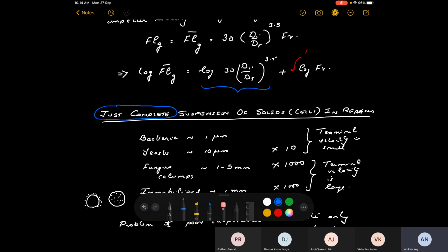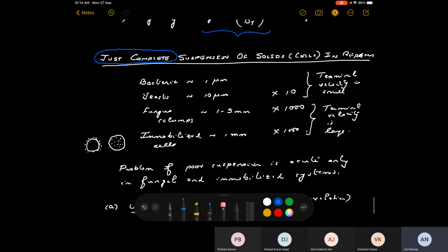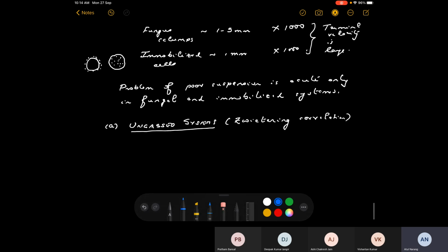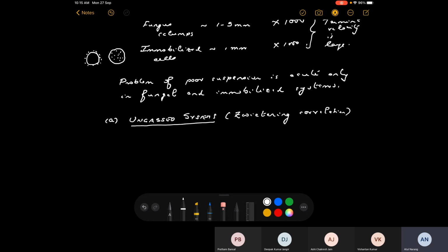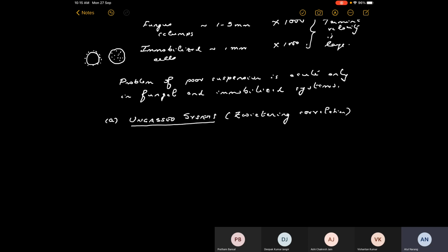This is different. In order to have perfect mixing of the cells, you actually need much higher impeller speeds, which will be covered in the next section on good liquid mixing. If you have good liquid mixing, it will simply carry the solids around. And what Zwietering concluded, based on experimental studies, was that this minimum impeller speed required for just preventing the particles from settling, he calls it NJS.